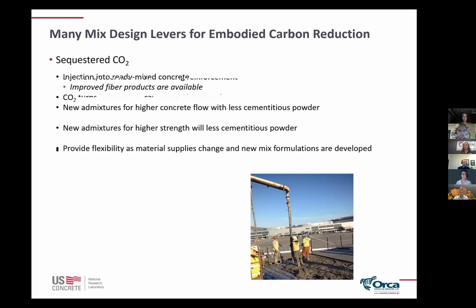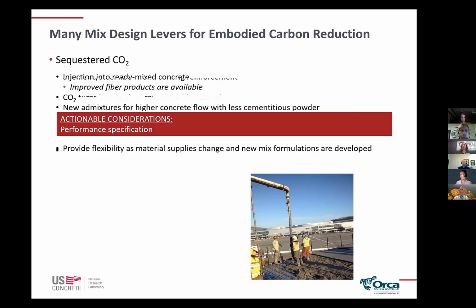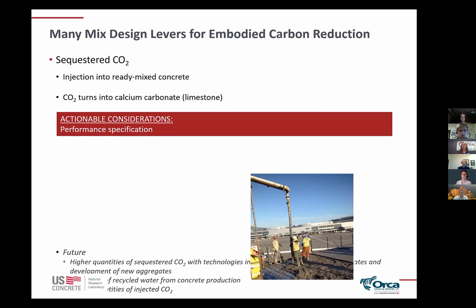And then sequestered CO2, this is kind of some of the newest topic out in terms of concrete sustainability. Carbon Cure has a technology for injecting recycled CO2 into ready mix concrete. Everyone that's working with CO2, kind of the idea behind it is that with concrete, you have the elements in place to be able to turn the CO2 into calcium carbonate, which is limestone. And so with this, a performance specification encourages the use of this.